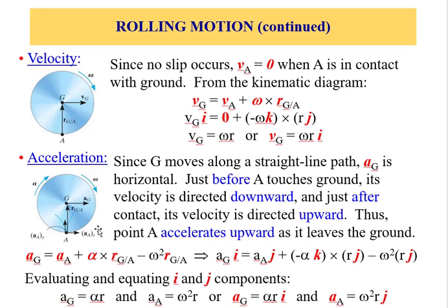and the acceleration at A is simply in the direction of y, because we said the point doesn't slip, so there's no horizontal component. It should be upward, and that's absolute. So we gave it an AA j. So we want to compute how much that acceleration AA, the acceleration at A, is.